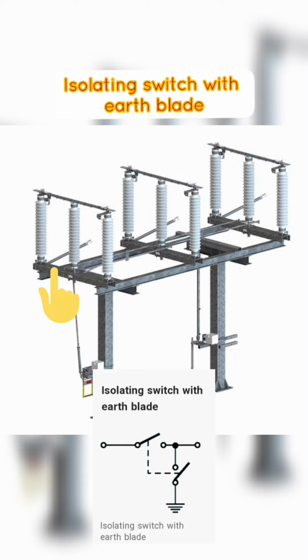Isolating switches are designed to be operated manually or automatically and are typically used in conjunction with circuit breakers and other protective devices to ensure the safety and reliability of the electrical network. They are also used to isolate equipment for maintenance or repair work, allowing technicians to work safely on the electrical system without the risk of electrical shock.